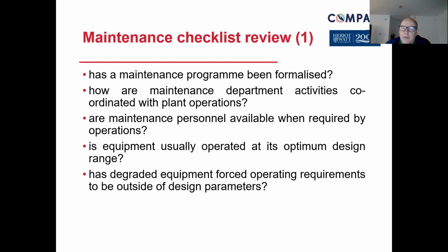Similarly, if you look at lifting operations and lifting equipment regulations and the need for thorough examination on lifting equipment, let's say a forklift truck as an example, if you push it to its limits, which we're asking the examiner to do, they take in a load, let's say it's capable of lifting 2 tons, they would work out the safety factor and say, well, I need to push it to 2.5 tons.